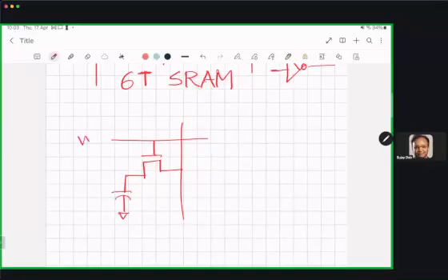So this is your word line. Basically, the row you want to select to read or write, you will be selecting it by enabling this word line. And then there is this line, which is basically your bit line, which depends on what you want to do. You want to write something. For example, you want to write a 1 in this. So what you will do, you will make this bit line 1. You will enable this word line.